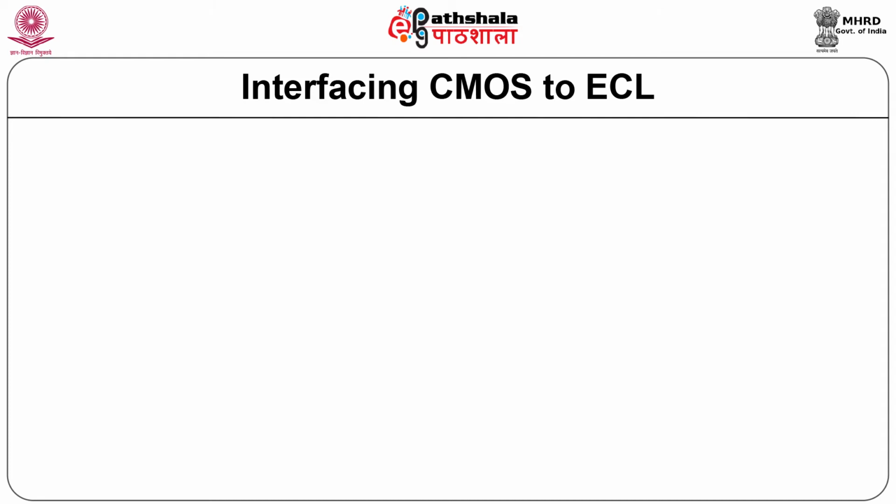CMOS to ECL and ECL to CMOS interface. CMOS to ECL and ECL to CMOS interfaces are similar to TTL to ECL and ECL to TTL interfaces. Again, dedicated level translators are available. MC10352, for instance, is a quad CMOS to ECL level translator.